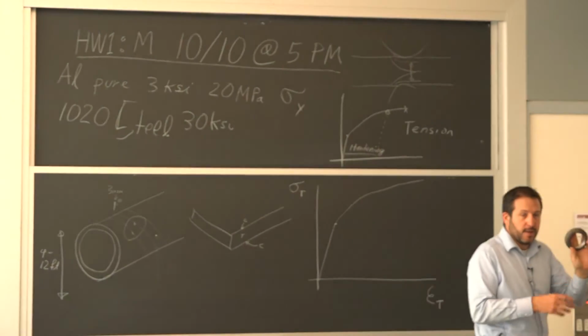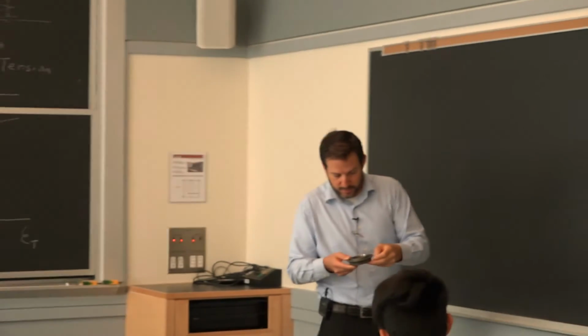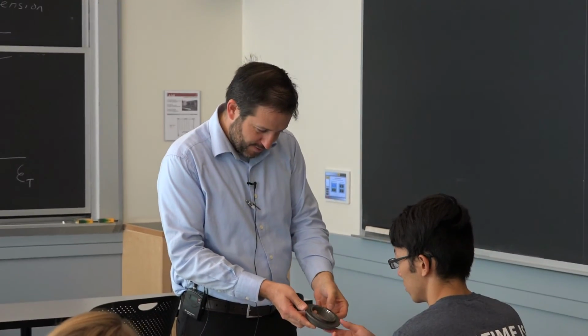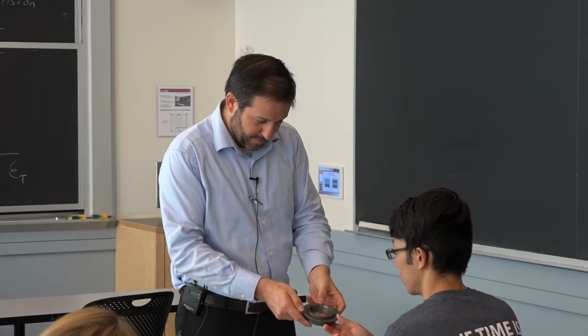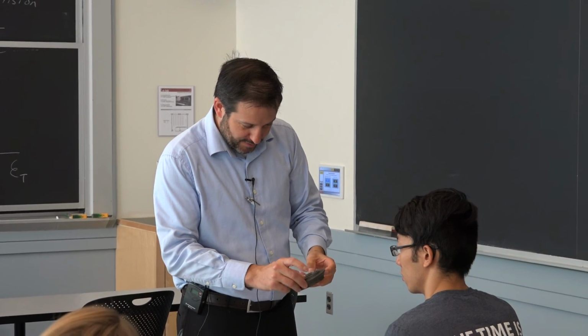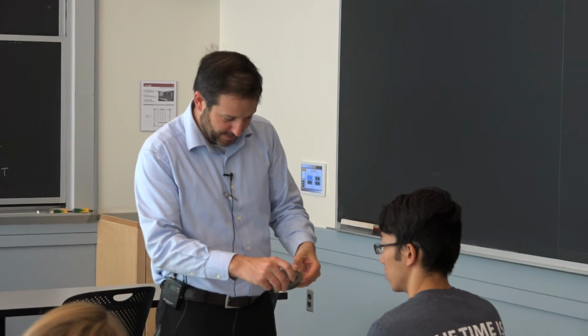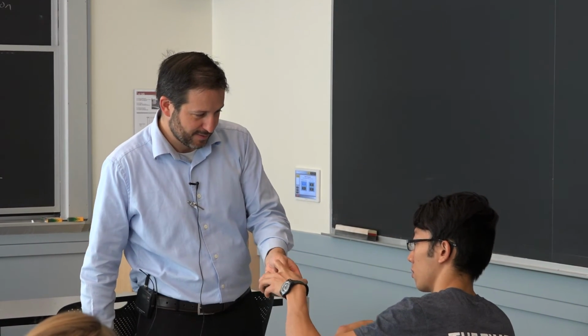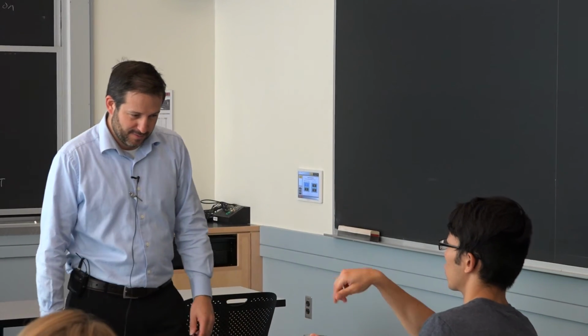If you didn't know at first, the first time I picked up this piece, I wasn't sure it was a forging. But when you flip it over, you'll see that lip here. It's not regular all around, that lip. That's not from a casting or machining. This is essentially the proof that this was forged as opposed to anything else. So it was initially forged and then drilled?